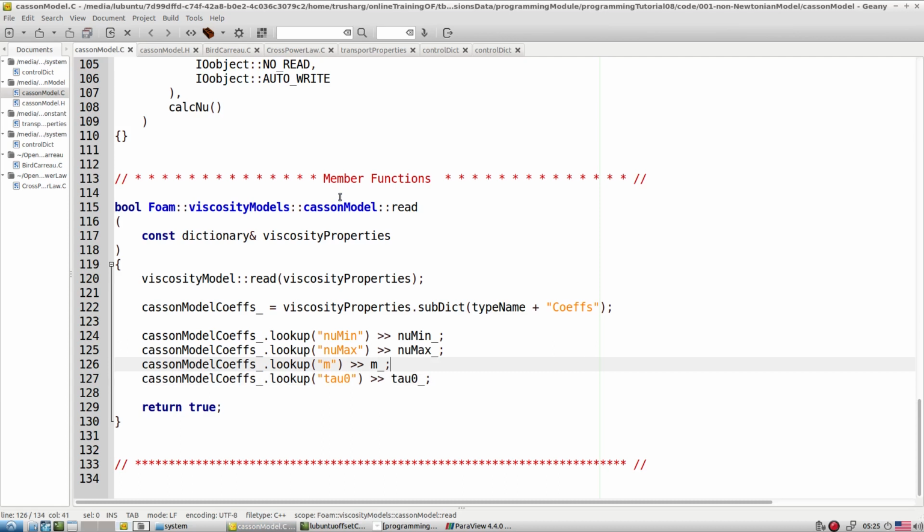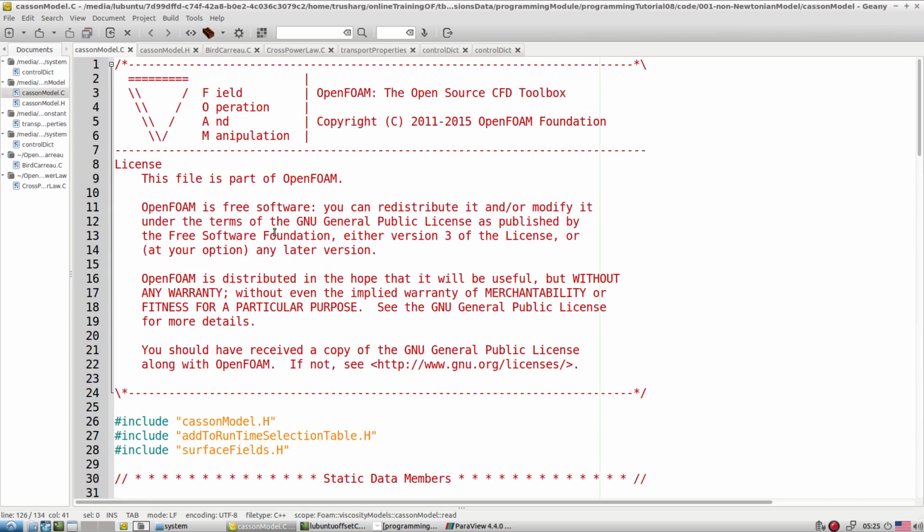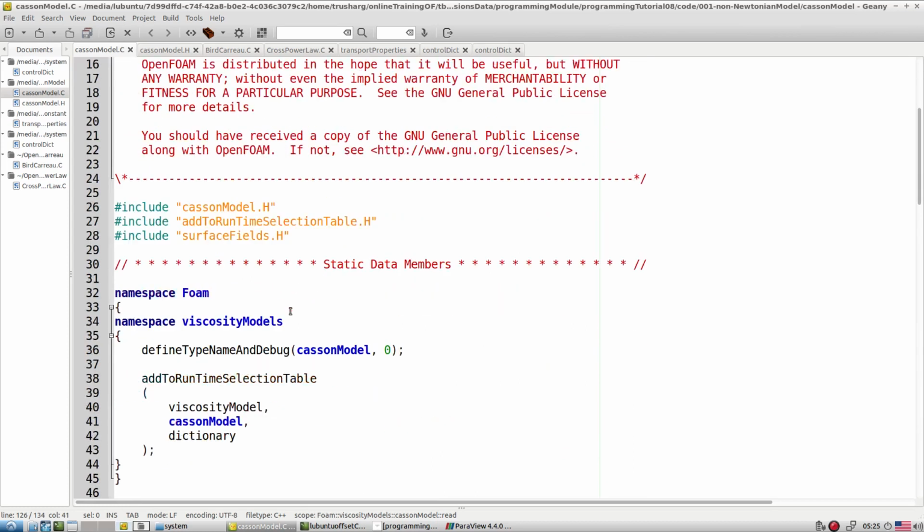So I suggest you establish one test case, flow through a channel or a pipe, because we know that in the laminar zone, for a Newtonian fluid, we definitely get a parabolic profile with the peak 1.5 times the mean value. But with this non-Newtonian model, you will not see the same peak. So it is the testing of this non-Newtonian modeling.